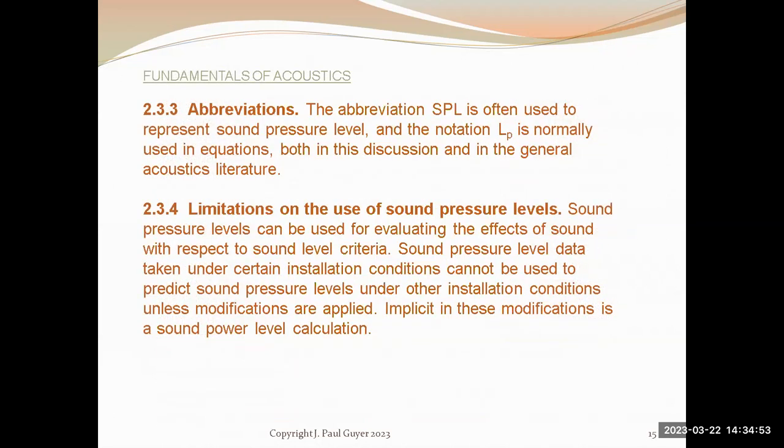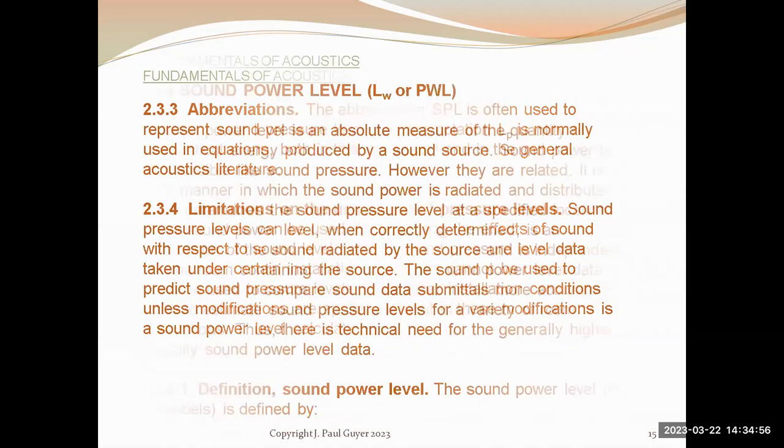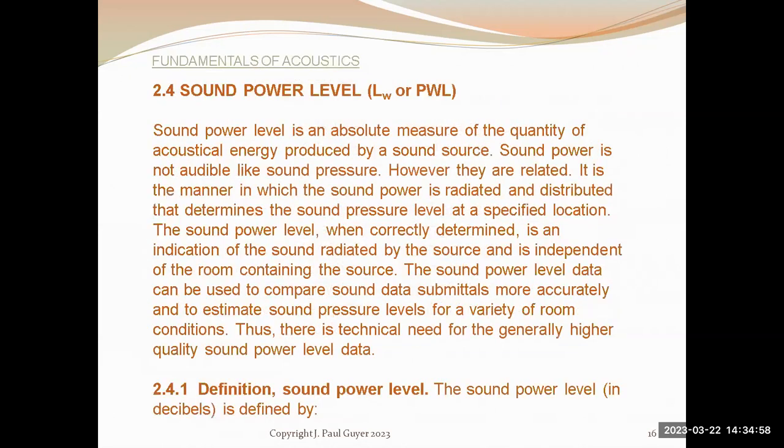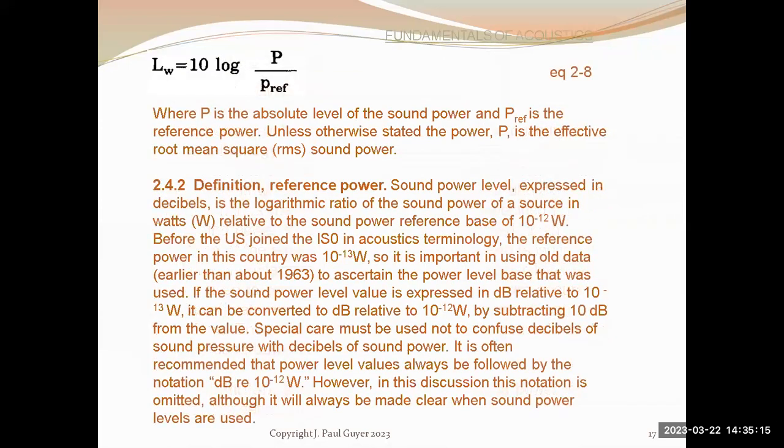Okay, now sound power level is the measure of the quantity of acoustic energy produced by a sound source. It's defined by equation 2.8. The sound power level is equal to 10 times the log of the sound power being perceived divided by a reference sound power.